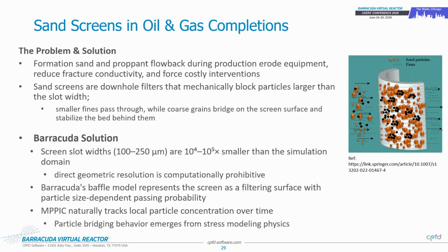So there's a lot of sand mitigation strategies that these companies plan around, such that you can keep producing oil at decent enough flow rates, but can you stop producing some of these sand particles? Producing sand fines is okay because sand fines are suspended in your liquid and they get transported. But how do you do that, right? A classic example, as you can imagine, is a screen, a filter. And they call it a sand screen filter down here.